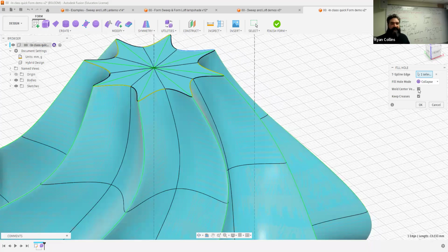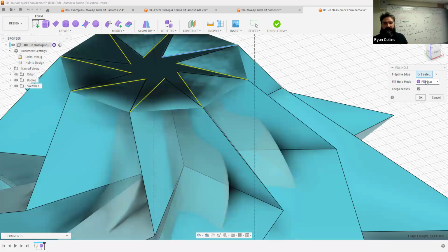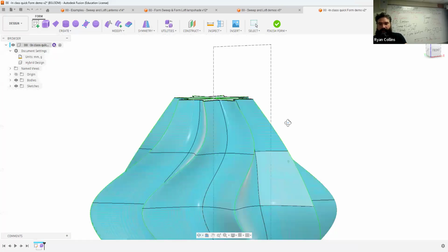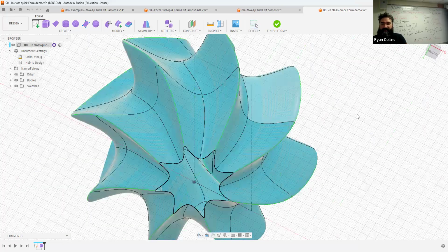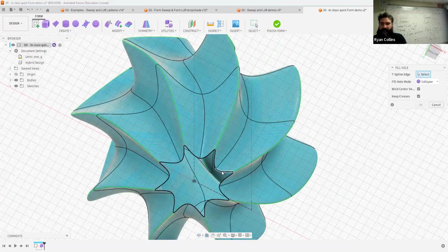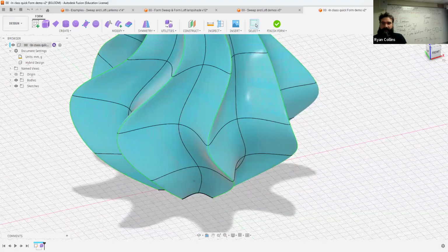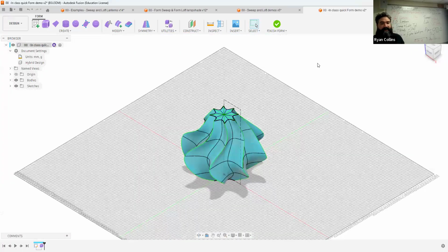Weld some vertices, I would definitely do, because it fuses everything at the top. Now, normally, fill star actually works very well. In this case, apparently, not so much. So we're going with collapse. That keeps it flat, keeps a star shape right in the middle. Hit OK. Repeat for the bottom, because it doesn't do it on both sides. Double click, and it should save all my presets. Great. Now I have created a solid whole object or an enclosed object.